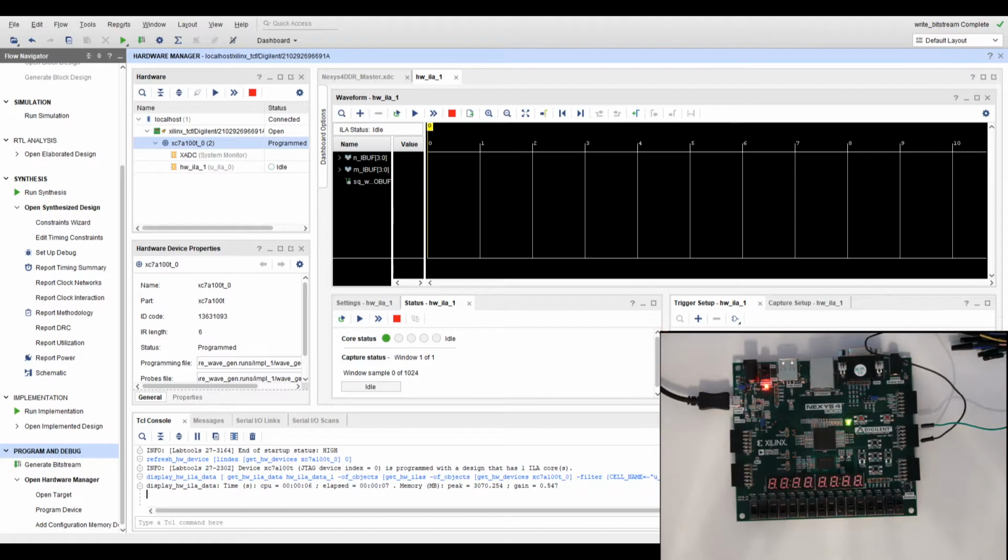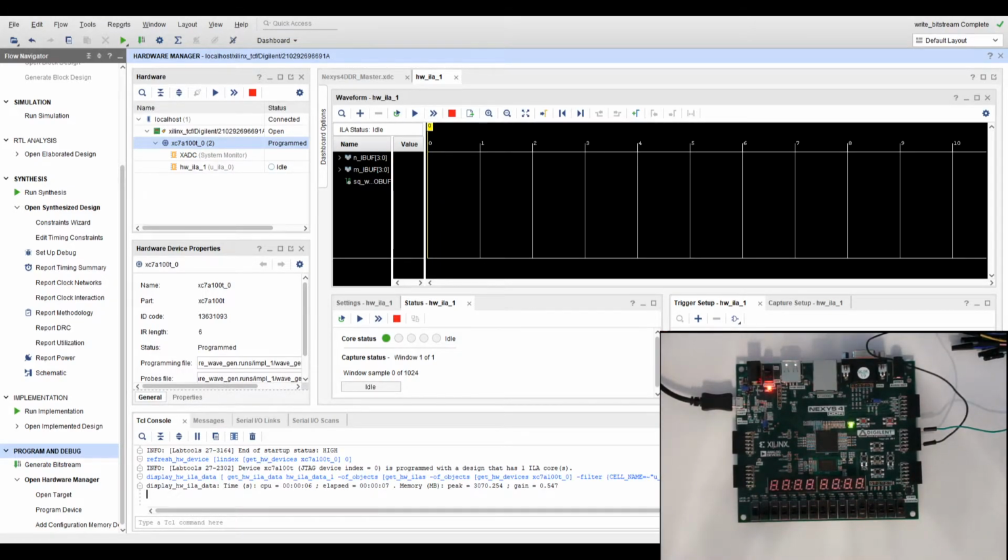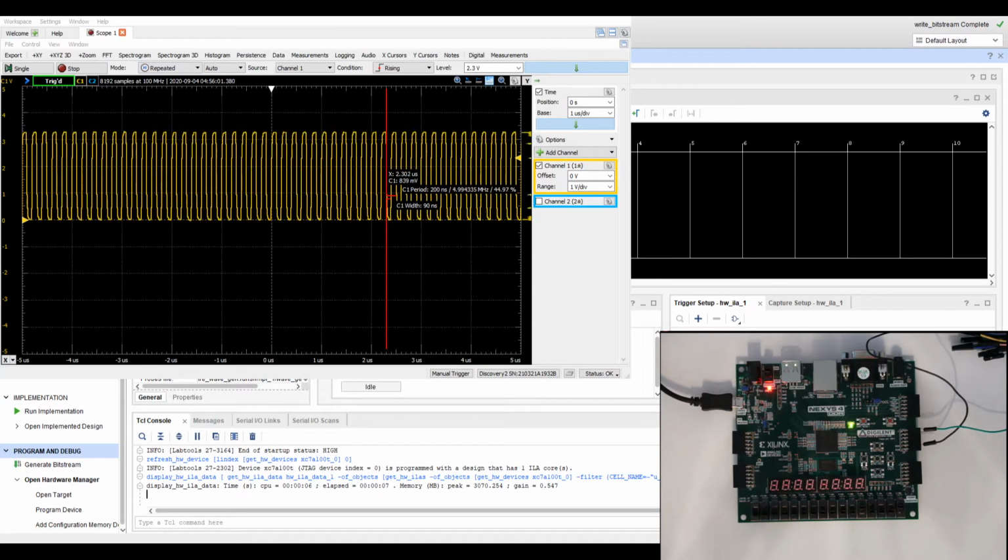Okay, so I'll show you, here's the FPGA now, and you can see nothing is appearing on it. I have these slide switches connected to the M and the N. The first 4 I believe are M, the second 4 are the N. I will just set them up now to be exactly 1 and 1. That's the easiest thing. Okay, 1, 2, 3, and 4, and this is 1, and we get to see it. So now if you see this waveform in here, you're going to see that I have that particular signal, and it should be 100 nanoseconds on, 100 nanoseconds off, and this is what I see in here. Very, very close to 100, not exactly 100.